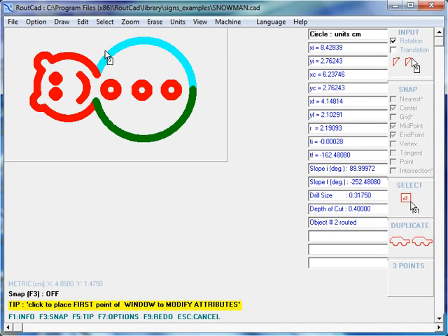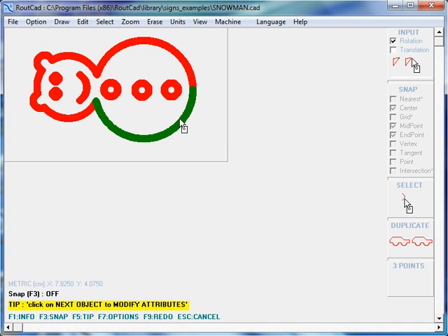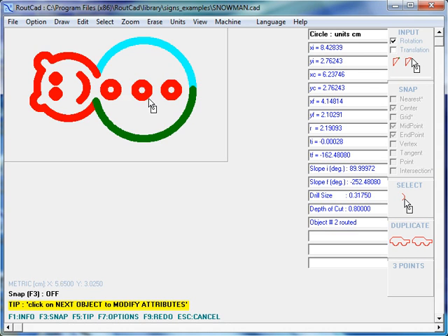The reason why is that when we did the window selection, the edge of the element wasn't within the window. But that's okay. We'll click over here to select segment selection, and we'll just click on it, and then it changed to 0.8. Now, if we click any of the outer elements, it is 0.8, and the inner element is 0.4. So everything is fine. It's going to machine the outer element by 0.8 and the inner element by 0.4.